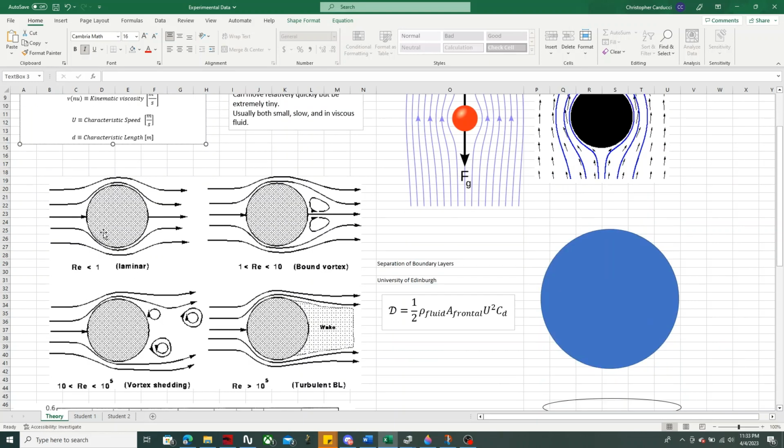The main thing that you have to worry about is skin friction, right? So the fluid is rubbing up against the surface, and then the fluid has to then interact with itself. That's where you're going to get most of your losses. But we see as Reynolds number starts to increase, we see that the entire flow starts to change shape, right?